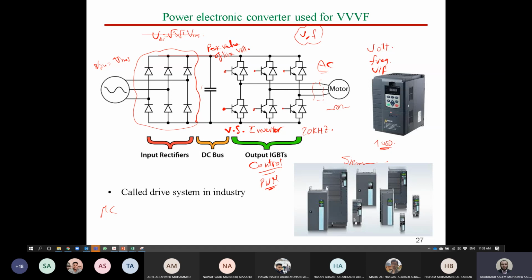What do you think about the PLC cost? It's very expensive, right or wrong? So we can use a PLC as supervisory control, not the basic digital controller. A PLC may control a lot of variable speed drives as a master control, not as a unit control.